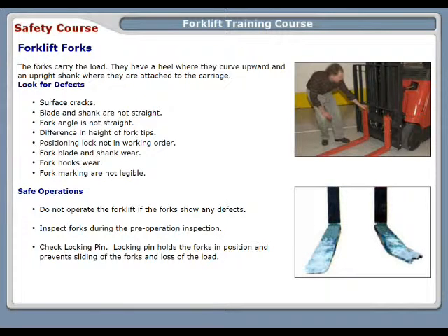Safe operations include: do not operate the forklift if the forks show any defects. Always inspect forks during the pre-operation inspection. Check the locking pin. The locking pin holds the forks in position and prevents sliding of the forks and loss of your load.